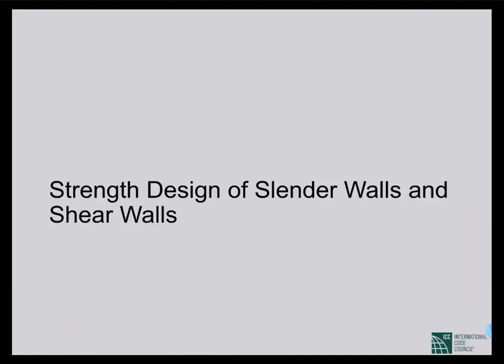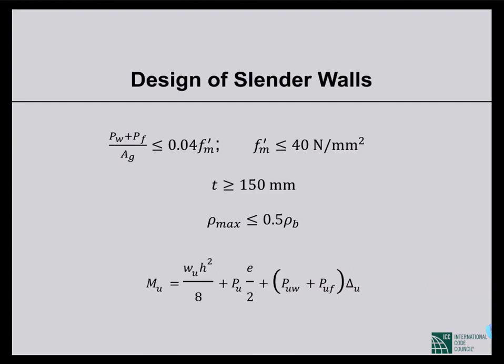Now, that was all about working stress design of unreinforced masonry wall or reinforced masonry wall. But there is also strength design method, but that is particularly for slender walls and shear walls. Slender walls are defined when the axial load is much low compared to its strength.